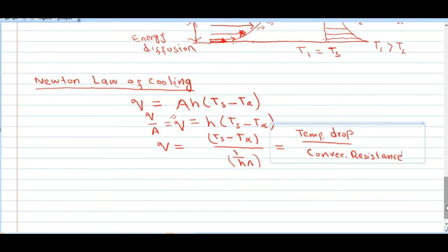Heat transfer by phase change also occurs due to convection, because during phase change there is either boiling or condensation. During boiling, the vapor rises and leaves the surface of the liquid. Since the vapor leaves its position, there is convection heat transfer. During condensation, the vapors leave the body of the vapor and become part of the body of the liquid. That's why heat transfer during condensation is by convection.